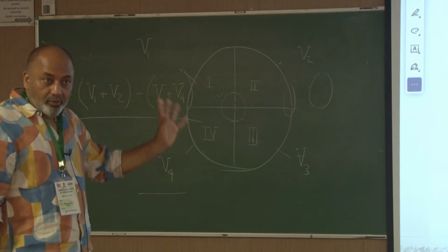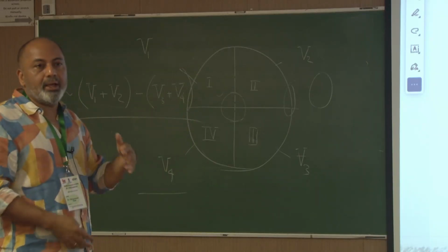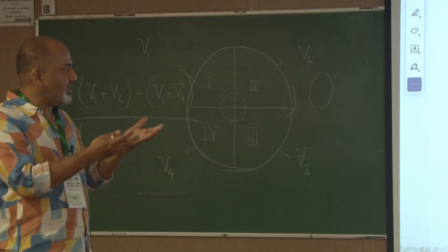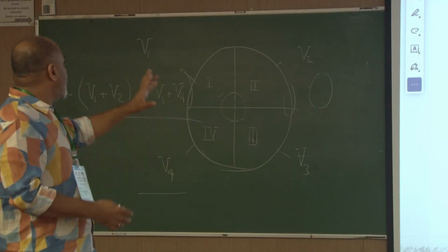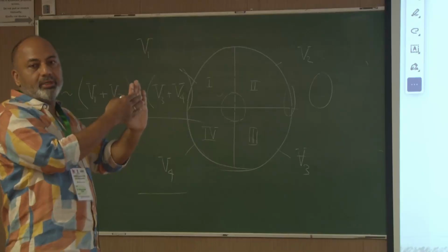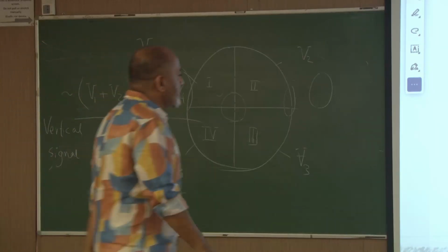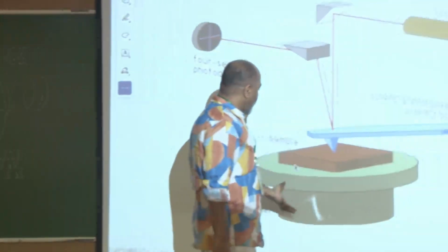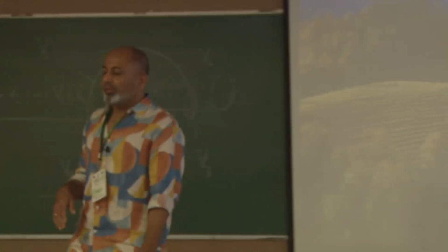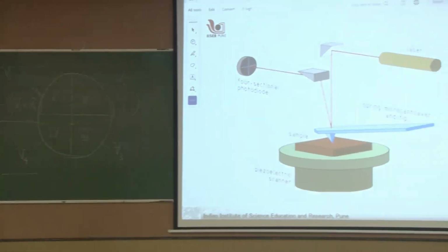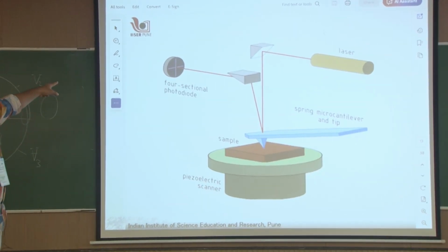And then the question is how, once again with the same calibration procedure, if I push the cantilever up by whatever force or distance, so that there is a bending in the cantilever, you will say, okay, if I get 1 volt signal, then I pushed by that much. So you have to independently know how many nanometers you push by. Suppose this is put into contact and pushed up by a nanometer. The end of the cantilever will move up by a nanometer, and since you know you moved the piezoelectric scanner by a nanometer, you can calibrate that nanometer to whatever volts.